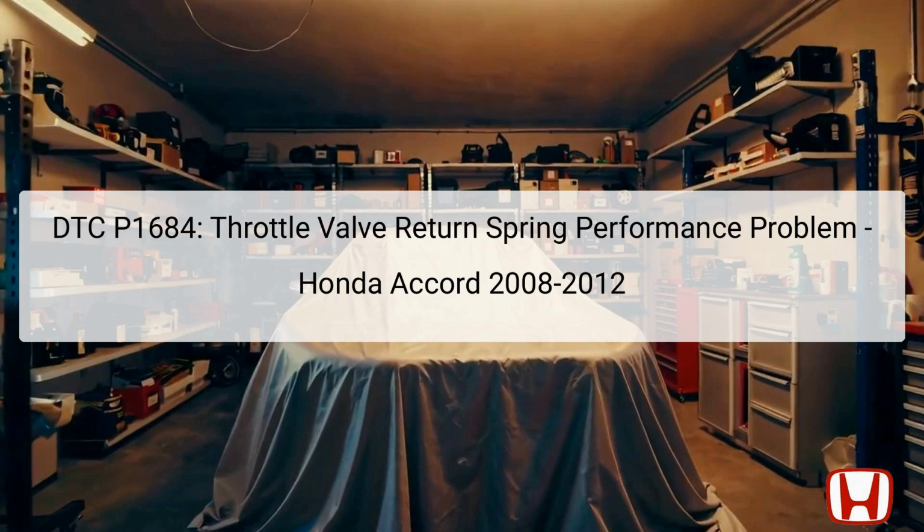The throttle body, which houses the throttle valve, is located between the air intake and the engine intake manifold. It is responsible for regulating the airflow into the engine based on driver input and engine parameters. A malfunction here can lead to poor engine performance, potential stalling, and increased emissions. Understanding this code and its implications is vital to ensuring the vehicle operates efficiently and safely.